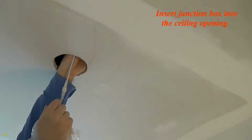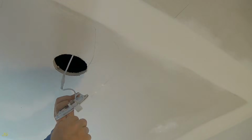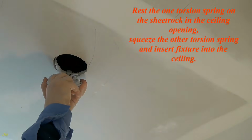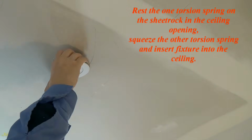Insert the junction box into the ceiling opening. Rest one torsion spring on the sheetrock in the ceiling opening. Squeeze the other torsion spring and insert the fixture into the ceiling.